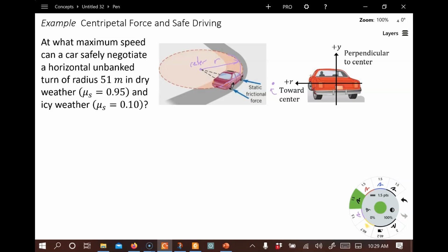So we've got the gravitational force, Fg, which is, of course, the non-contact force. Now we're looking for contact points on the vehicle. We see that we're ignoring air resistance. The only other thing we see here is the tires in contact with the road. That road is an external object which causes some forces to be exerted on the car. It's a surface contact, and so we're going to end up with two types of forces. One is the normal force, one is the frictional force. And for both of these types of forces, we know it's actually spread out over 4 tires. We're going to ignore that and just assume we'll draw single force vectors to account for all the 4 tires at one time.